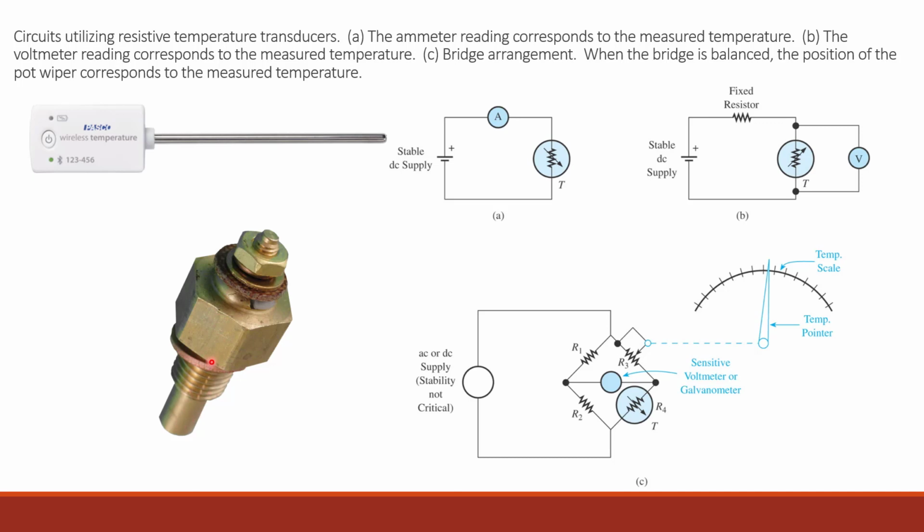As the temperature rises, the resistance changes so that I can measure the current that's going through that resistor. And as the resistance goes up, because the temperature is going up, the current's going to go down. I can translate that, or the voltage that develops because of the changing resistance, into a temperature change.